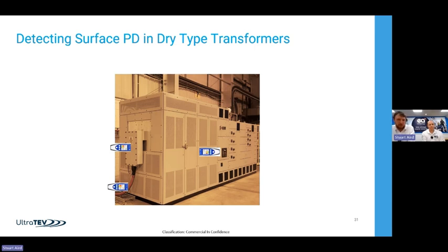There's air vents right round, but there's also a lot more open connections, a lot more dust, etc., collecting in there. Lots of other failure modes that creep into these transformers that are more likely to give you surface activity that we can detect ultrasonically. So you're taking measurements in a lot more locations. You also, from an ultrasonic point of view, do have the challenge of 50 hertz hum, the natural hum and load variations of a transformer. So that's something to be wary of.